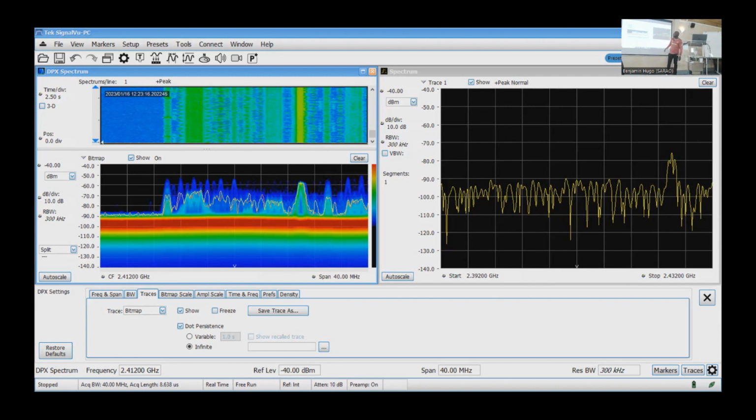So what you can do is set the analyzer, like you mask it. You mask the non-signal, and then you tell the spectrum analyzer that when you see something that is beyond here, capture it and then stop running. Or you can tell it to make a sound when it captures it and then stop running. So later on, after you've taken your coffee, maybe 6 hours, you come and see, oh, I captured it. Then you start analyzing that particular signal. That's how you start to analyze the electromagnetic environment of a particular place, but also to do EMC measurements.